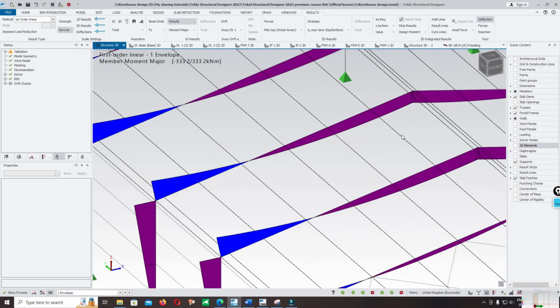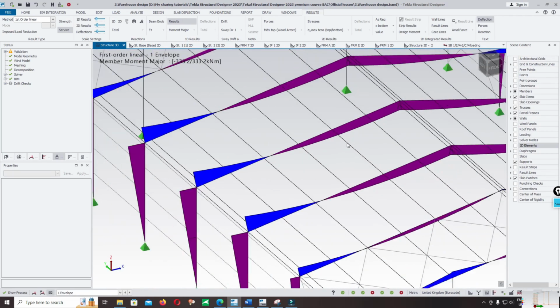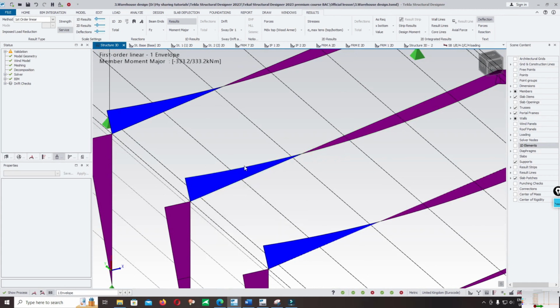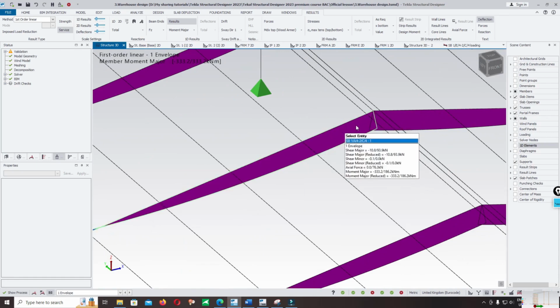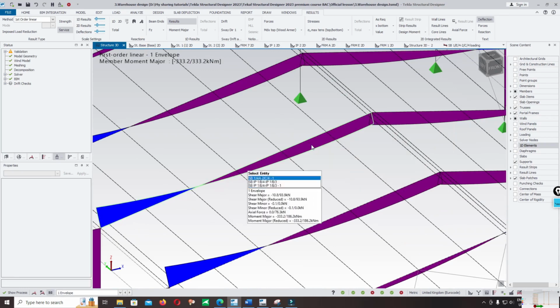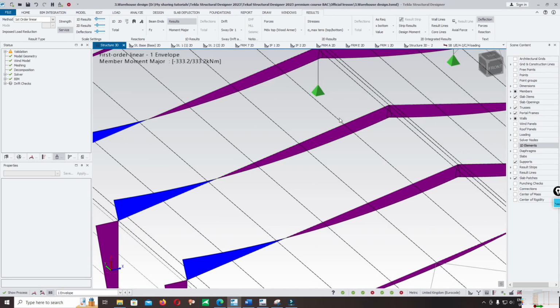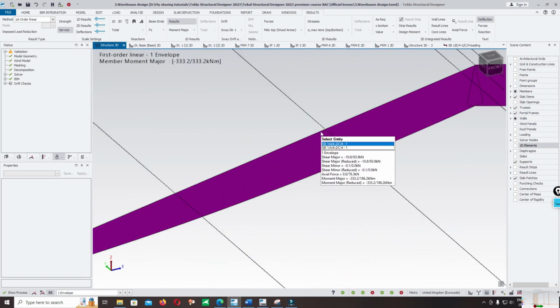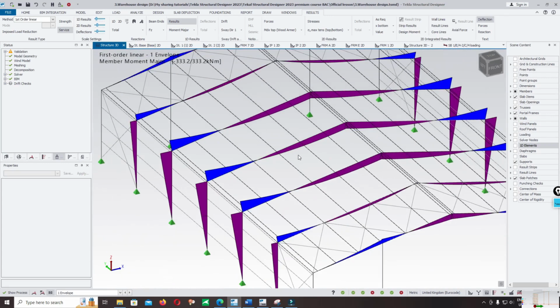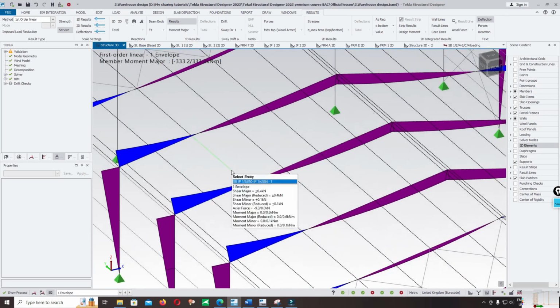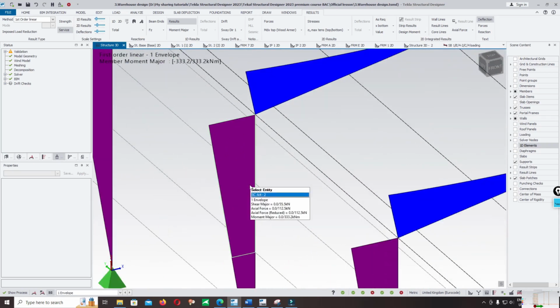This is the way you know how to add restraint on the beam and on the column by checking the envelope force moment. This is tension at the top of the flange, and this one is tension at the bottom of the flange. So the top flange is in compression. In compression, we can add the torsional restraint in the location, and for the location you can add at the intersection. It's optional, but in my design code I add it at every intersection of the purlin with the rafter. For the column it's the same.